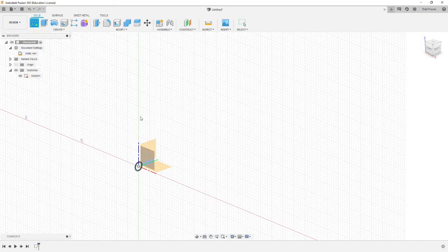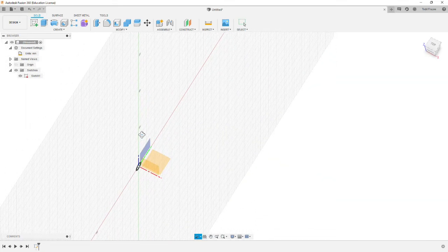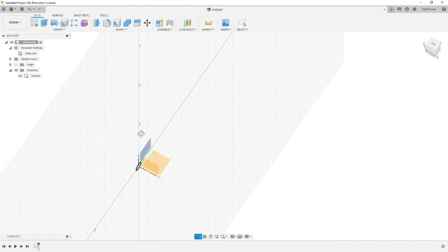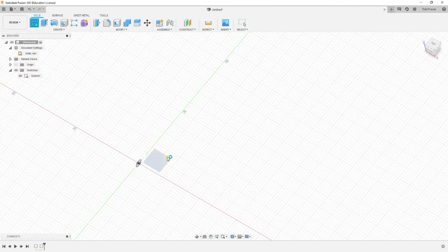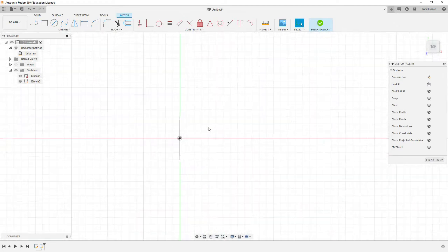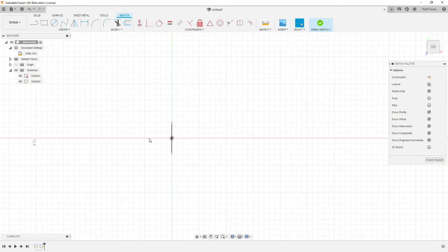So we're going to go to the sketch menu and we are going to sketch in the top plane. Now we're looking on end at our circles, and we're going to start with the short end of our path. So we're going to draw a line, and that's going to be horizontal. Then we're going to come back and draw a radius by stretching the line. So you go back and pick on the existing line and stretch it, and it switches to an arc. And then we're going to go straight up.